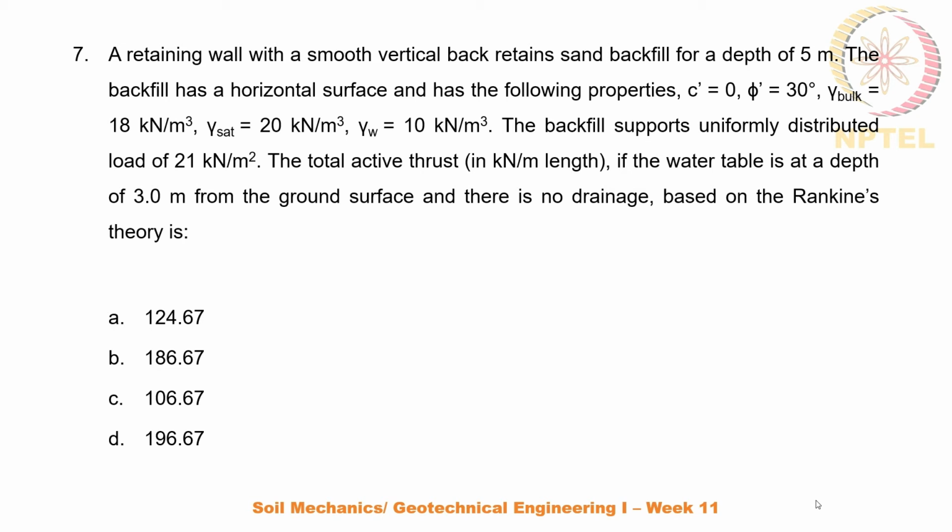But in this problem, the water table is at a depth of 3 meter from the ground surface. And also there is no drainage. So the backfill is submerged from 3 meter below the ground surface. So we are asked to determine the total active thrust in that case.